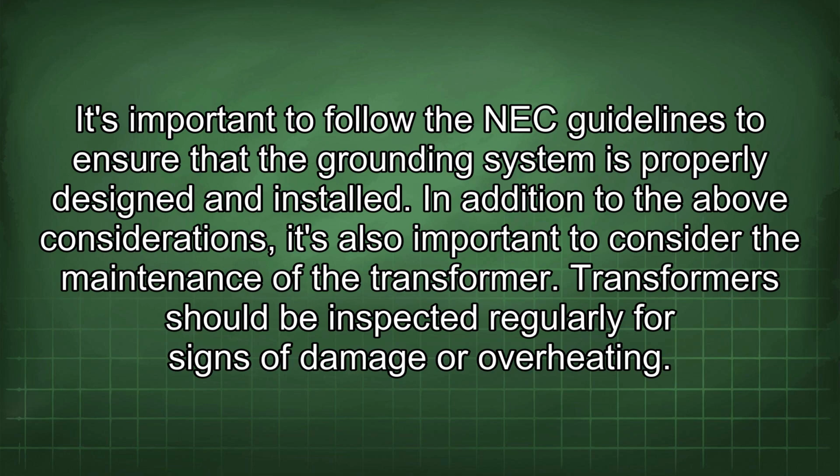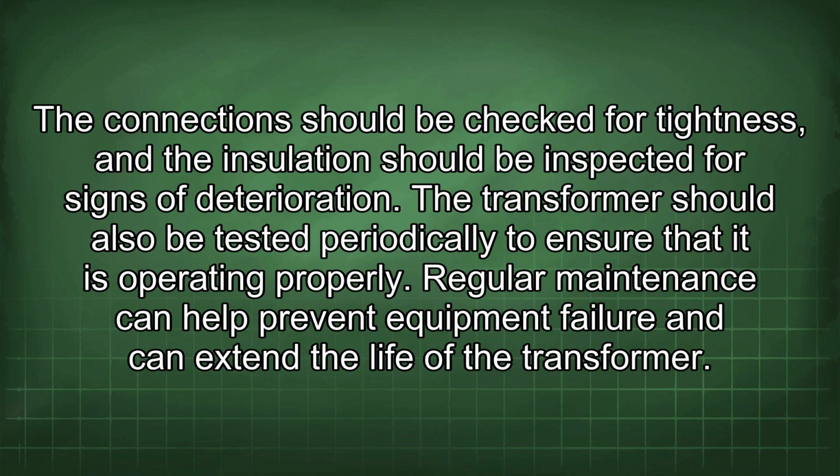In addition to the above considerations, it's also important to consider the maintenance of the transformer. Transformers should be inspected regularly for signs of damage or overheating. The connections should be checked for tightness, and the insulation should be inspected for signs of deterioration. The transformer should also be tested periodically to ensure that it is operating properly. Regular maintenance can help prevent equipment failure and can extend the life of the transformer.